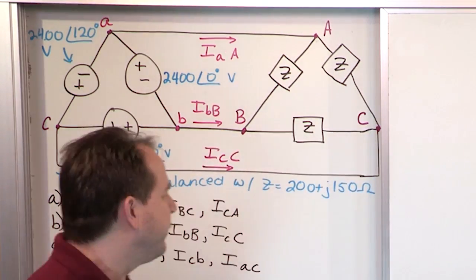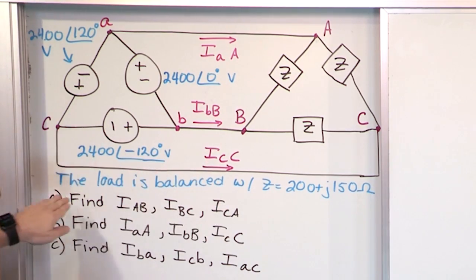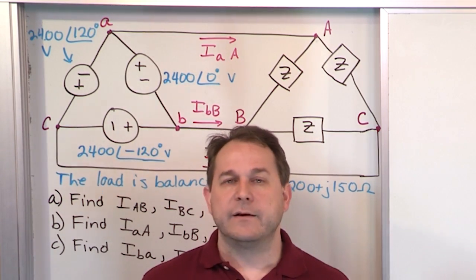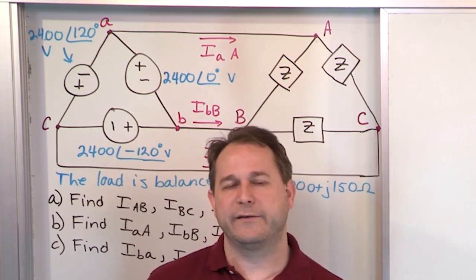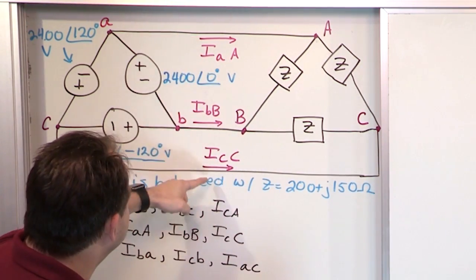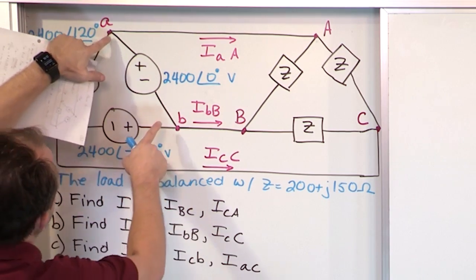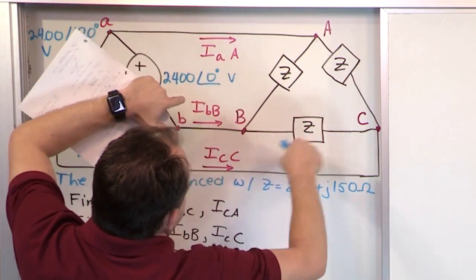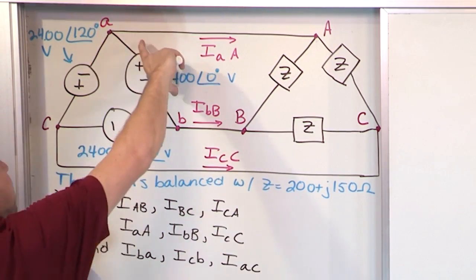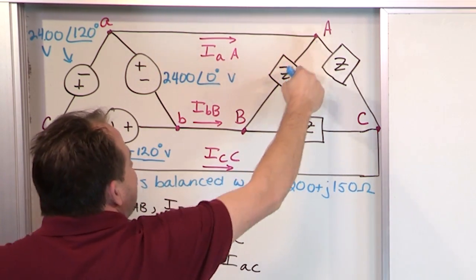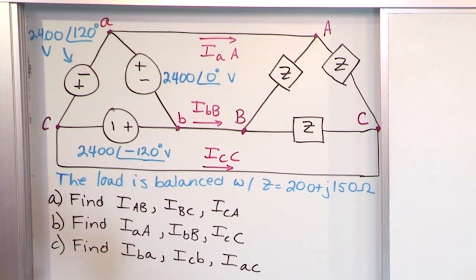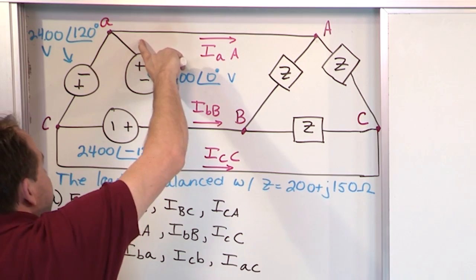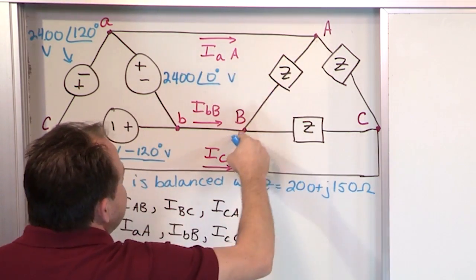All right, so first things first, how are we going to find this guy? Normally, for the currents in the load here, we're going to draw a single phase equivalent circuit and all of that. However, this is a very simple case, so we don't need to. Because we don't have any impedances here at all, the voltage between A and B is physically connected to this load over here, Z, and all of these are the same, so it's connected across here. So because you know the voltage drop physically across here, you can calculate the current directly. You don't need to write any single phase equivalent circuit because there's no impedance here at all. In other words, there's no drop here at all. So all of this voltage lies entirely across this phase of the load.